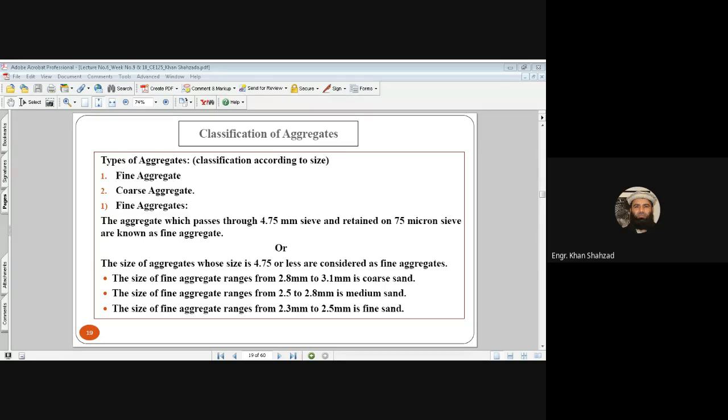इसके अलावा मैंने आपको बताया था कि जब अर्थक्वेक आता है तो अर्थक्वेक का जो फोर्स होता है, it is directly proportional to the weight of the structure. अगर वेट ऑफ द स्ट्रक्चर ज़्यादा होगा तो अर्थक्वेक फोर्स ज़्यादा अट्रैक्ट करेगा, और जो डैमेजेस, क्रैक्स स्ट्रक्चर में होंगे, वो ज़्यादा होंगे। तो if you are using light weight material and light weight concrete in earthquake prone areas, then there will be less chances of damaging of those structures. Is it okay? Yes sir.